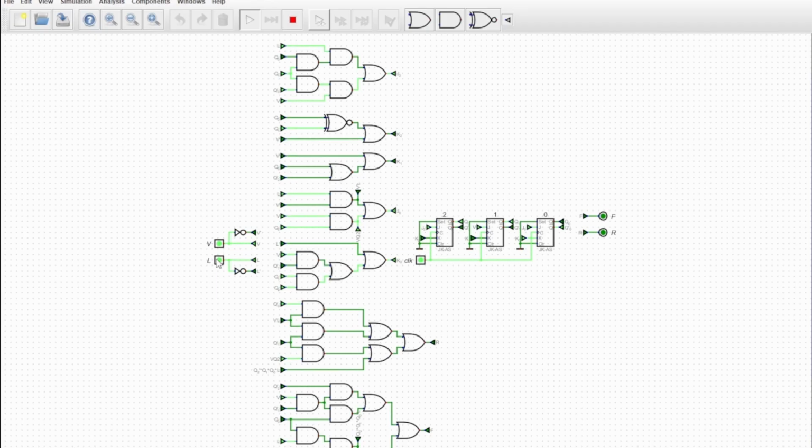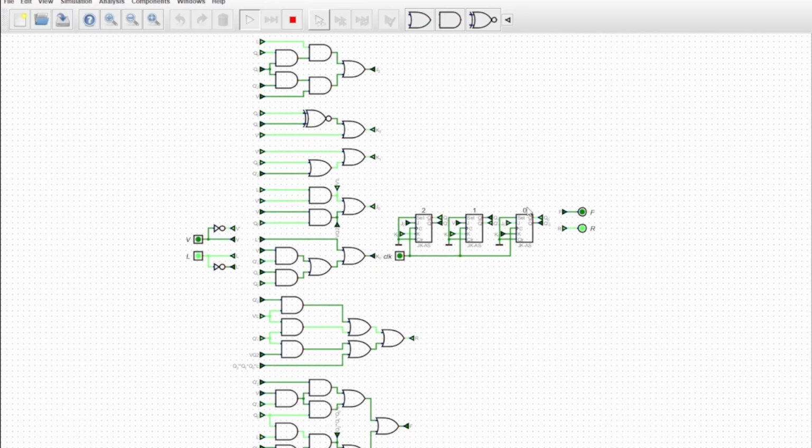And if we ever, by the way, if we ever have L back on, as you can see, R comes back on immediately. So essentially what's happening is, after turbo mode, and actually I can show you, if we reclock this, so if I go into turbo mode, oh, I need to turn both on. So I'm in turbo mode here. If I ever turn V off and then clock it, as you can see immediately, R turns back on. So that was one of the things I had in my state diagram, where I wanted every single, like S5, S6, both route to S1 if V ever turns off.